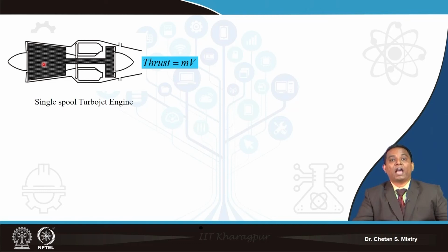Now when I say I am looking for a higher pressure ratio, that means the number of stages required for this axial flow compressor will be larger. That will increase the length of my engine, and that is a constraint for my aero application. The second option: you may be aware of the fundamental equation called Euler's equation, which we will discuss at a later stage. That is, the power generating or power absorbing capacity of turbomachinery is a function of my rotational speed.